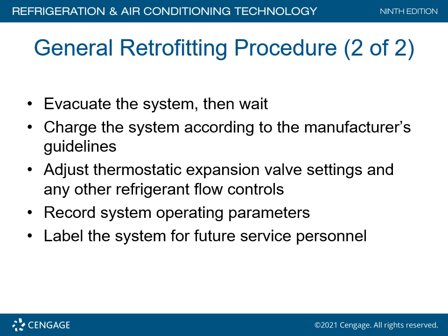If you have a system that contains R22 and is low in refrigerant, and you do not have R22 on the truck, but you have R407C as a blended refrigerant, the temptation is to take that 407C and add it to the R22 that's still remaining in the unit in order to get the charge level up and get the pressure temperatures to work. The problem is now you have a chemical that doesn't exist on the refrigerant pressure temperature charts. You are going to have an impossible time trying to predict the temperature and pressure approach levels of this mixture of refrigerants.